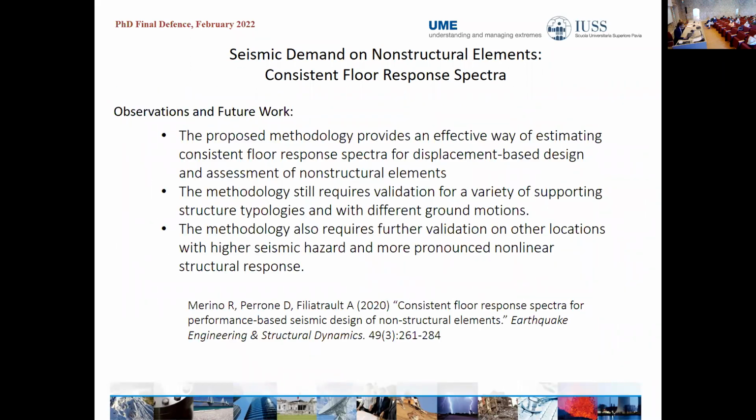So some observations and future work on this topic. The proposed methodology provides an effective way to estimate floor response spectra for direct displacement-based design and assessment of non-structural elements. The methodology still requires some validation with a variety of supporting structures with different seismic force resisting systems and with different ground motions. The methodology also requires validation on other locations with a higher seismic hazard that will induce a more pronounced nonlinear response of the structure. The main results of this study have been published in a paper in Earthquake Engineering and Structural Dynamics.